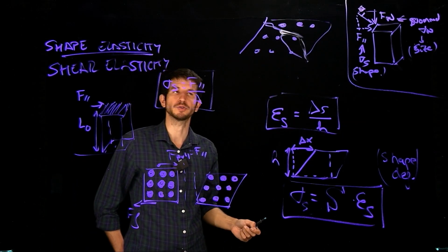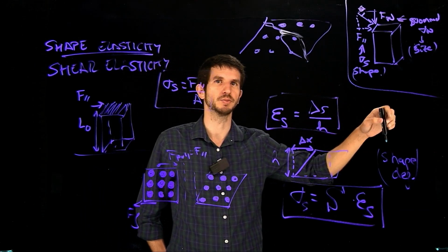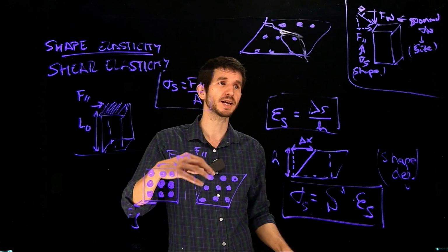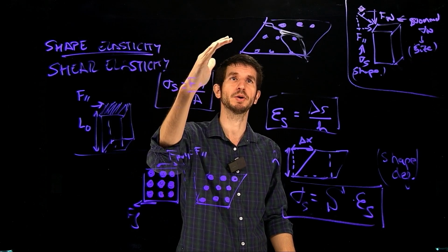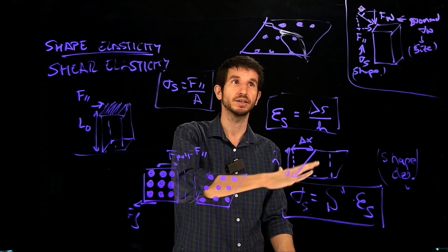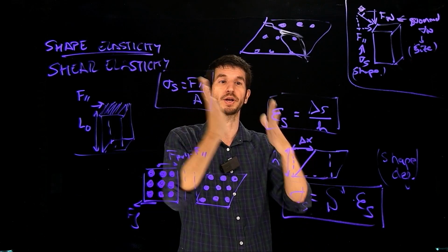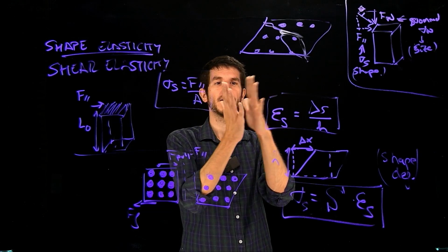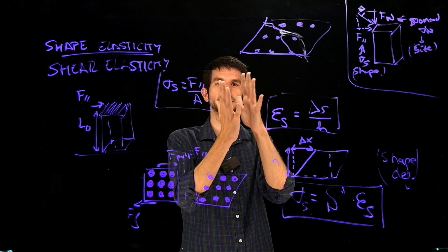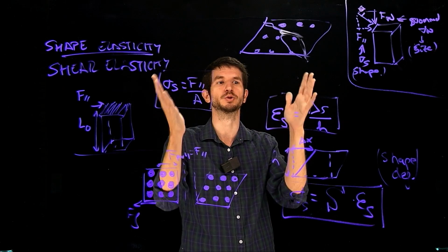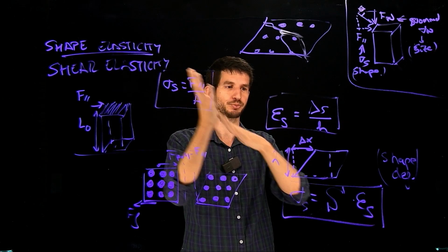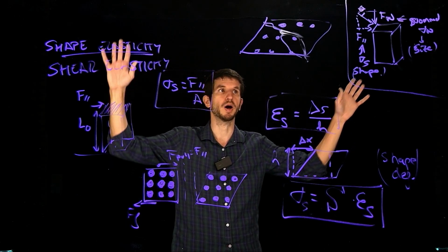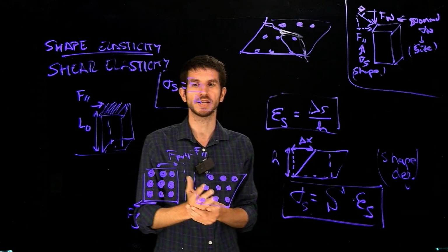So shear stress also can destroy it, when you go into the inelastic regime for shear stress. It doesn't need to be only about size. Example of this, let's say you're in snow in a mountain, there's snow, and suddenly there's an avalanche. Why that happens is actually there's a break. Layers of snow slide with each other, they don't have any more retention, the interatomic or interlayer forces, the interfacial forces keeping the surfaces together, van der Waals forces or whatever, they're not enough anymore. The thing breaks, you go to the inelastic regime, there is catastrophic failure. The same thing happens with mud in the mountains and things like that, right? So that's an example of shear force.